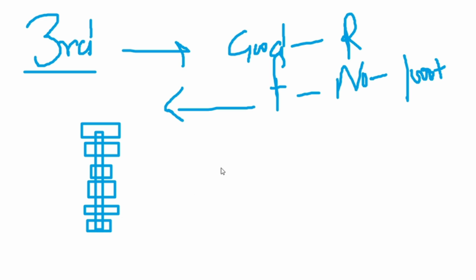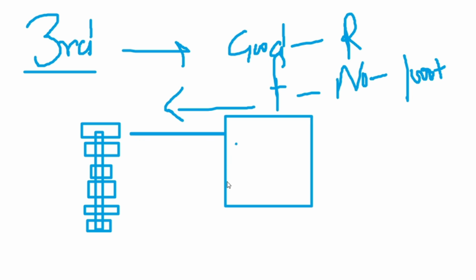If the fault still remains, you can confirm the fault is on the IC side. Any component is not okay, maybe this light IC or any capacitor. We will find it in hot testing. How? In the next step we apply hot testing, so you can confirm where the problem is.